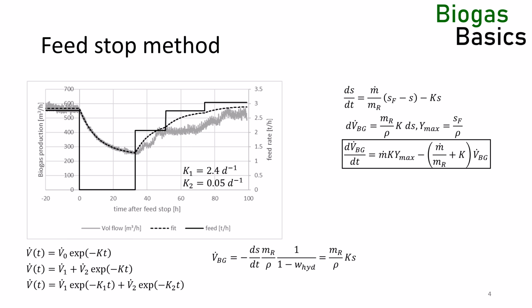One of the model assumptions is that the reactor is a CSTR, a perfectly mixed reactor. In reality, it takes a while for the fresh feedstock to be broken up and distributed in the reactor. In this example, feedstock has been fed via an auger system into a high viscosity reactor using laminar agitation. We could model the mixing behavior as well, but we are going to stop here, as we discuss microbial growth in this presentation and not digester agitation. For this, I have a dedicated presentation.